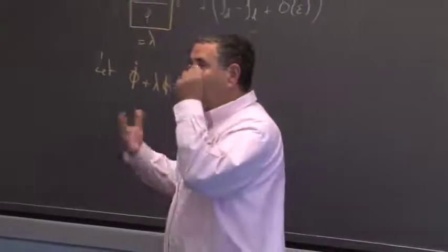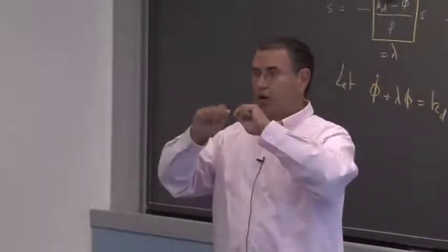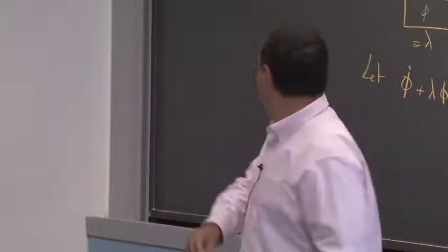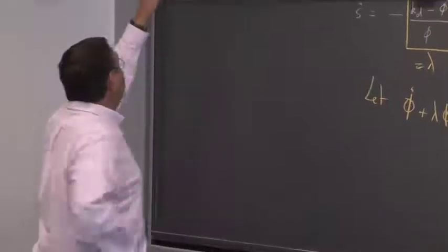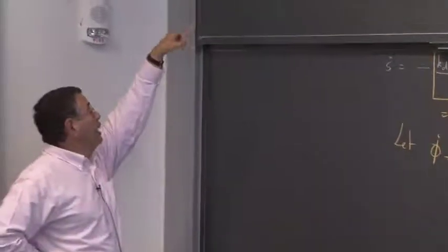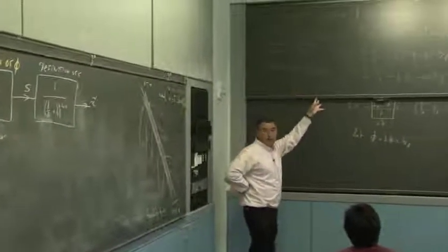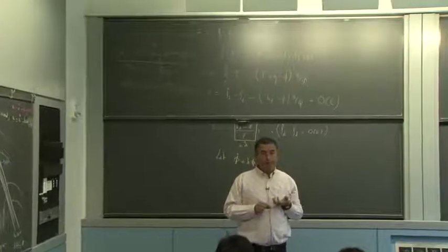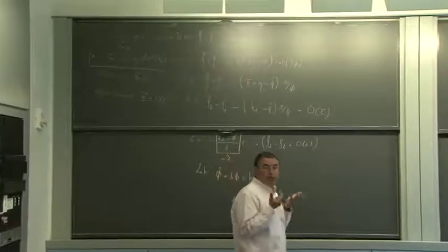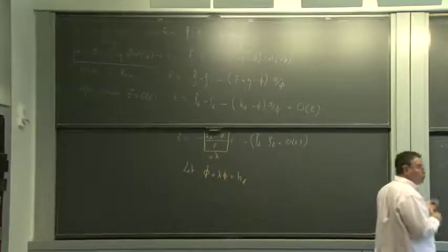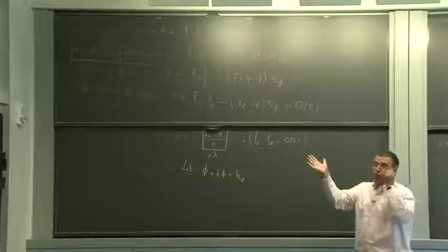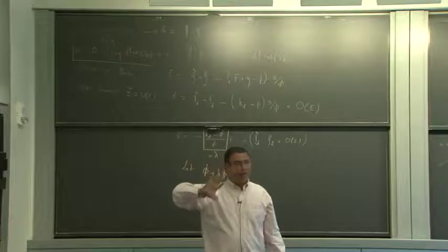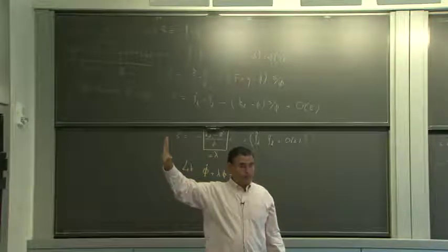Okay? So we started with uncertainty on f. That gave us k. This term k gave us u equals u hat minus k times sat of s over phi. We still had to define lambda and phi. For the moment, they were just numbers, positive numbers. Lambda we chose, we'll come back to that, to be nowhere near the time constant involved in the neglected fast dynamics in the model.